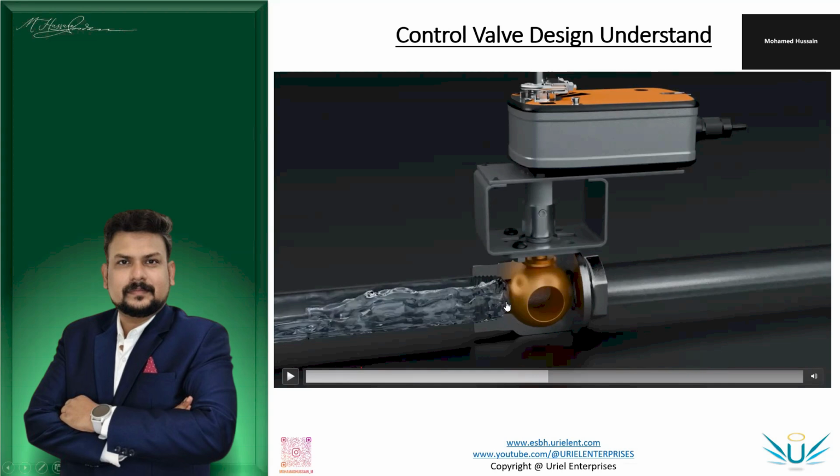It will flow outside the pipe because this pipe is connected to this valve. If you oversize, the flow will be more, and the pump will put more energy into pushing the water through the piping system. So we have to size the valve accurately.